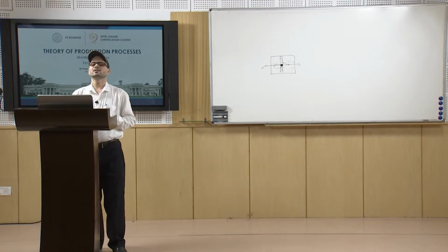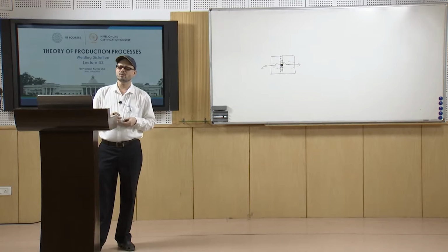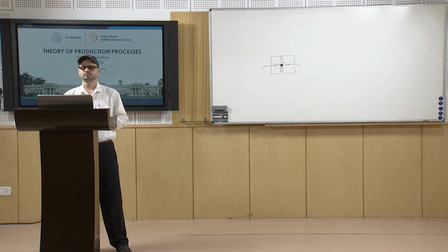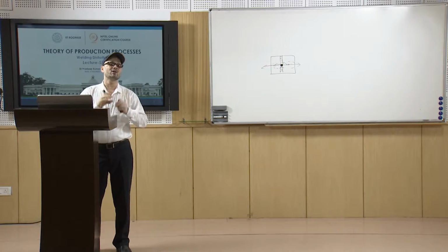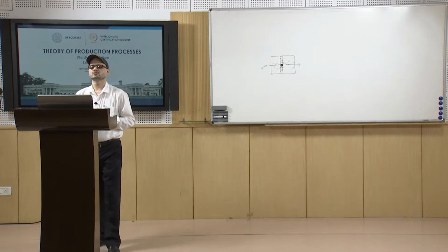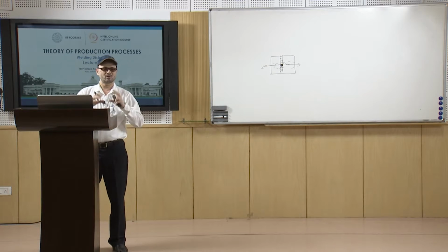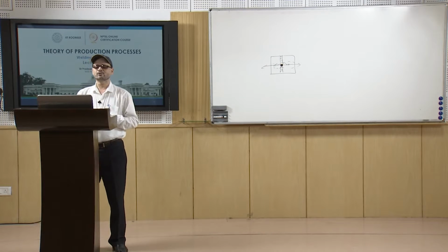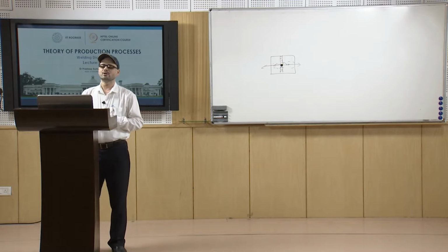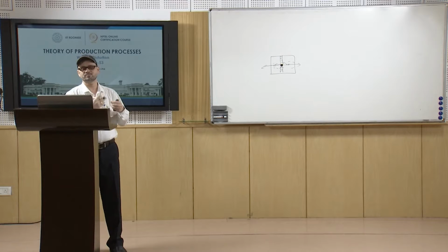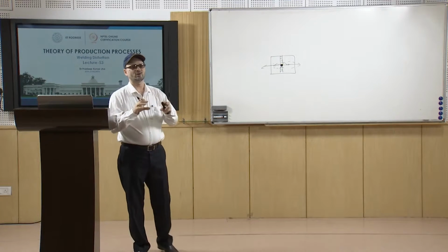important. Now, the amount of weld metal. When we talk about the amount of weld metal, the amount of distortion will depend upon the volume of the weld metal. Again, the volume of the weld metal which is heated will depend upon the welding process, like what is the welding speed, what is the heat input rate and all that.